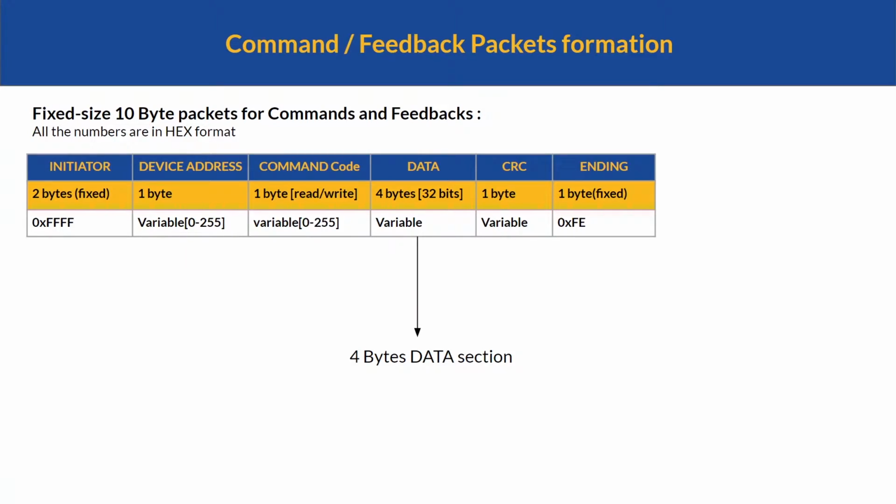The next section is a 4-byte part, which contains the data section. If your packet should tell or set a value inside Solo, the data should reside here. Also, for the feedbacks you read from Solo, the value of the feedback or the parameter that you are reading is stored in this section of the packet.